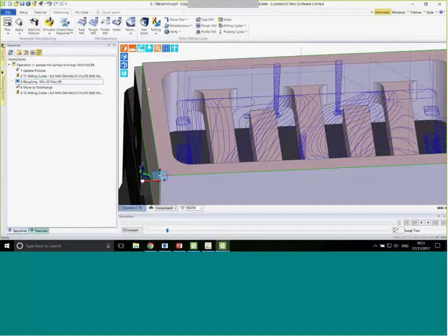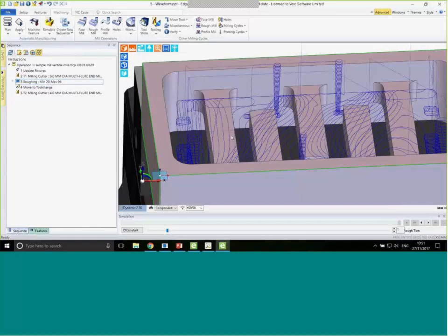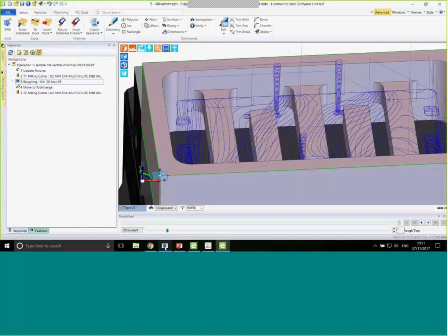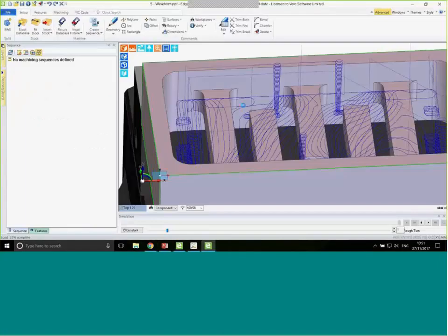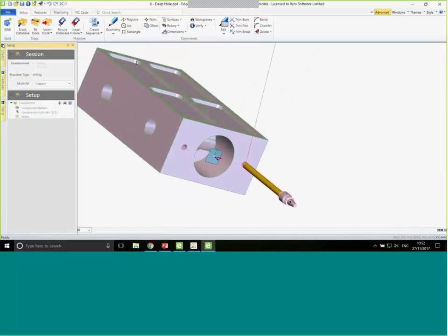Also, being able to determine the size of the radius is very beneficial. We get lots and lots of carbide users, carbide manufacturers whom we work with, asking us to state that value. Go 1.5 times the size of the radius, go 2 times the size of the radius. We've simply not been able to do that. Now, inside the roughing cycle, the helix parameter, you can determine that by having the maximum and the minimum.